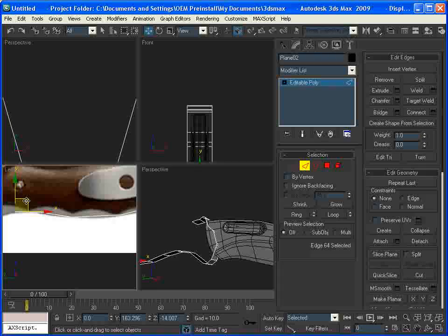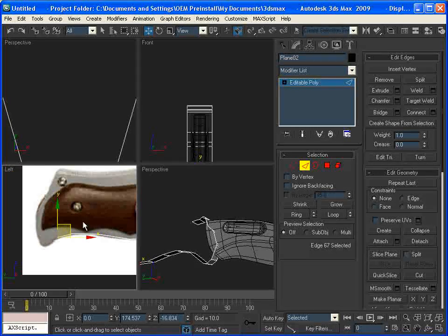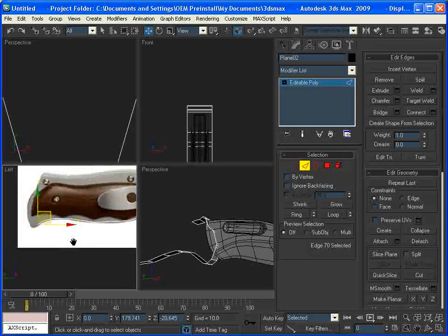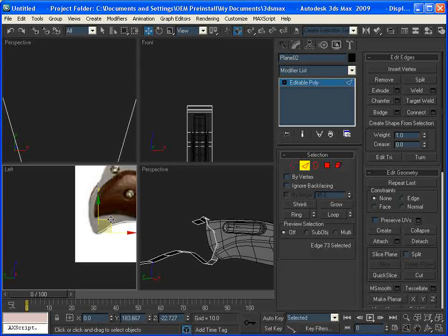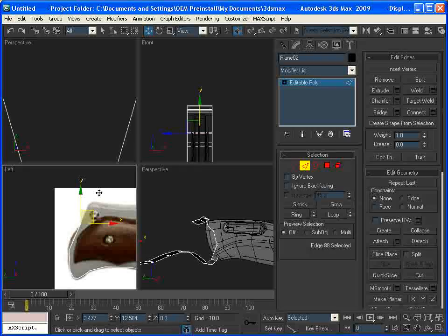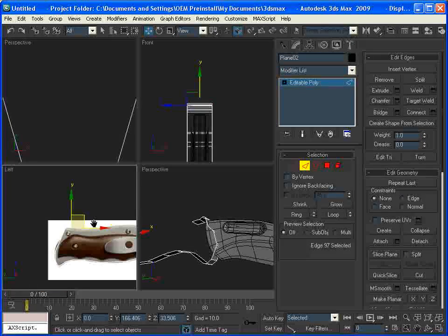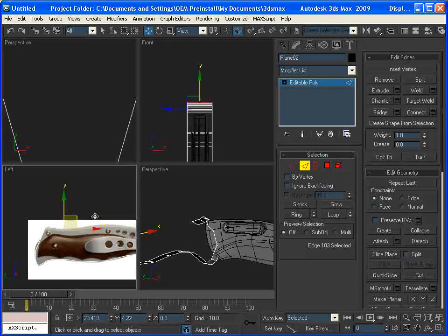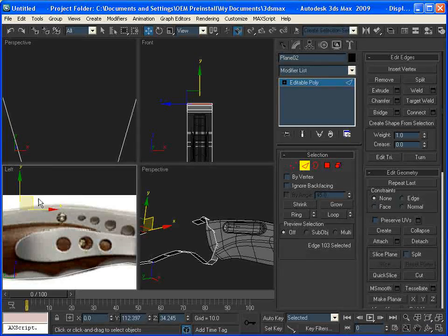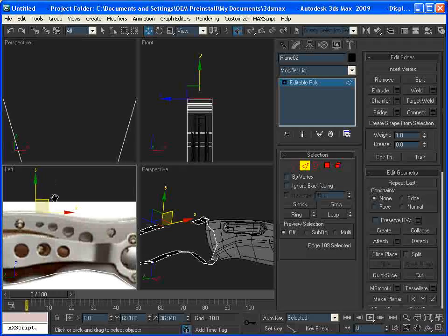If you tried to tackle this from the side, though, starting with the side first, it might be more difficult because of areas like this. You'd have to bridge things and connect them in awkward ways, but there's a much easier way to do this with subdivision surfaces that we'll get to in just a moment when I finish up here. It's much easier because you don't have to worry about n-gons in certain situations. So we can actually leave most of the side here open. Not actually open, just capped and without lines through it.